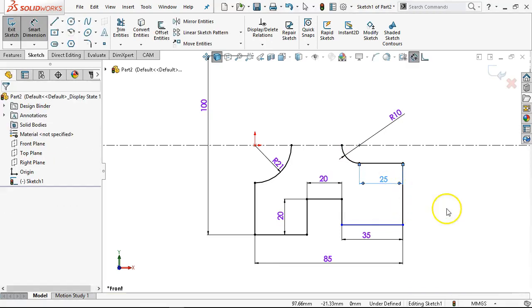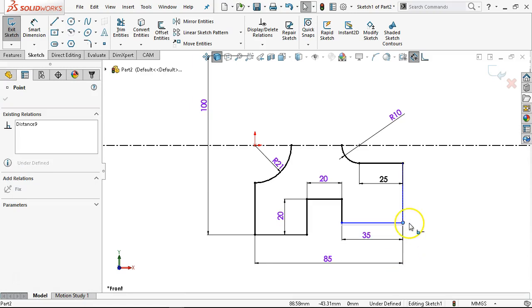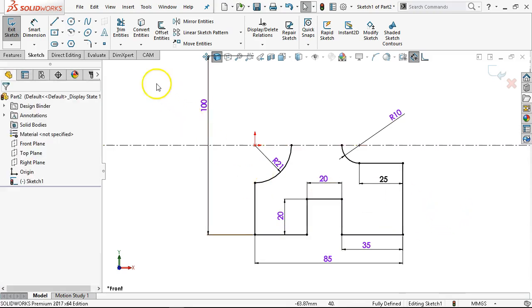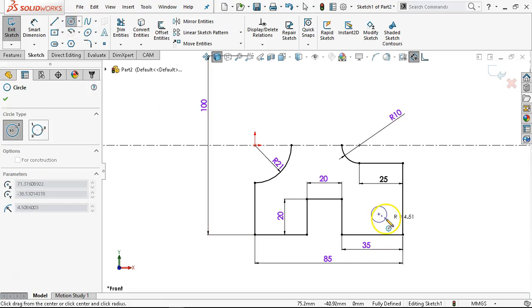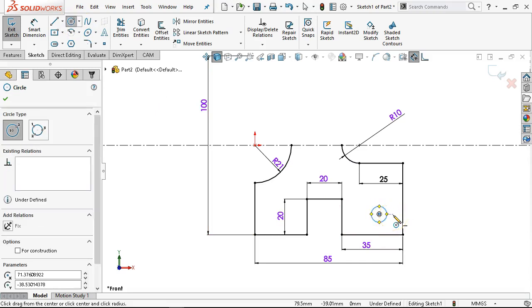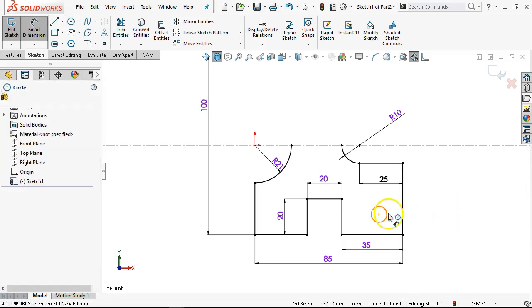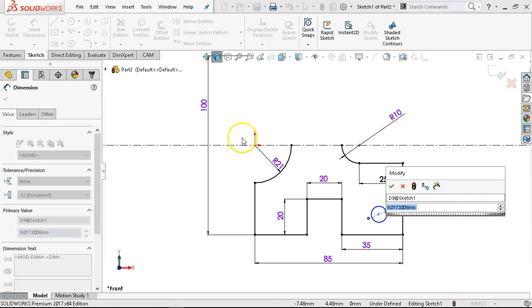All right, so everything's in black except for one line. And so we're at that point where we select, control select. The two objects will be collinear. An endpoint in the object would be coincident. I'm going to go with the collinear. We'll use this to introduce the fillet feature, since there are four corners, radius of 10. So I'm just going to leave those squared off. Actually, the next one has fillets too. Okay, we'll do sketch fillets on this one, and then the next one will be feature fillets.